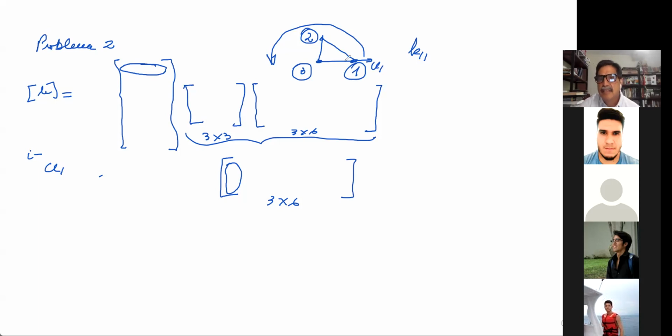So if I identify this as the first joint of this element, it will be much easier to identify the column and the row that I have to multiply in order to get K11. Don't you think so? And everybody did the other way. Name this joint joint 1. So in this case, you have to identify, I'm going to write like in red, so this is the third row, and this is the third column. But I think it's more complicated to do this instead of doing in blue.